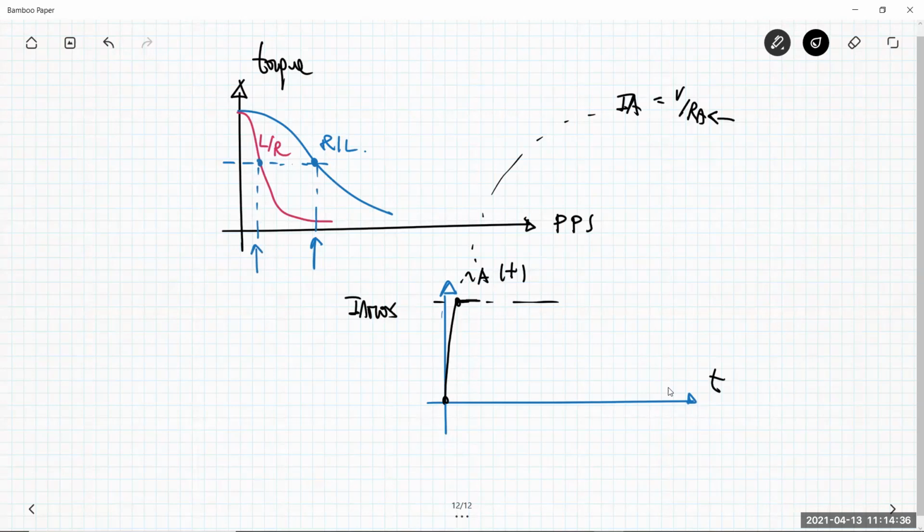If I have something that recognizes that I reached the maximum current provided by the datasheet of the stepper motor I'm using, and then maintains this current constant, I can always employ a voltage V as large as I want.